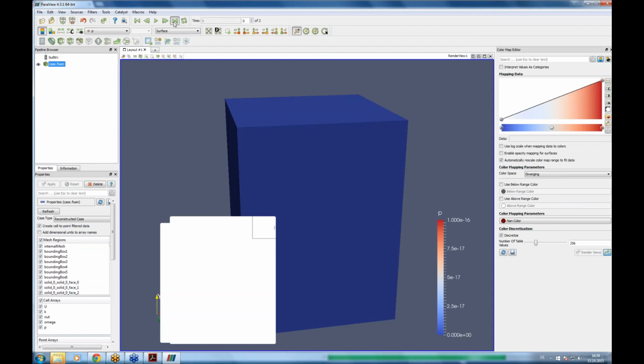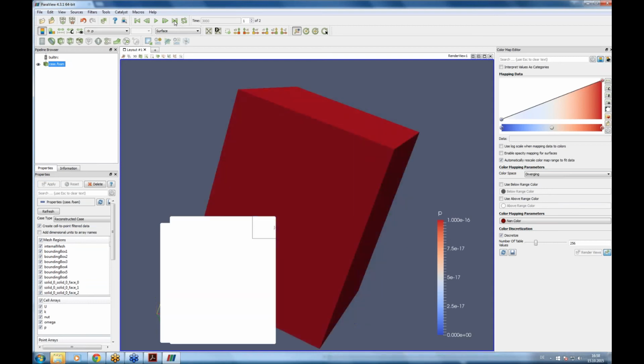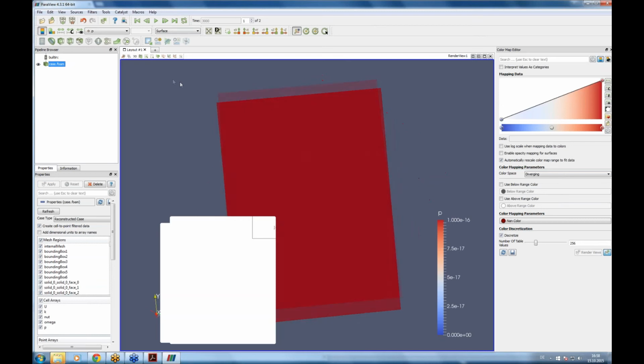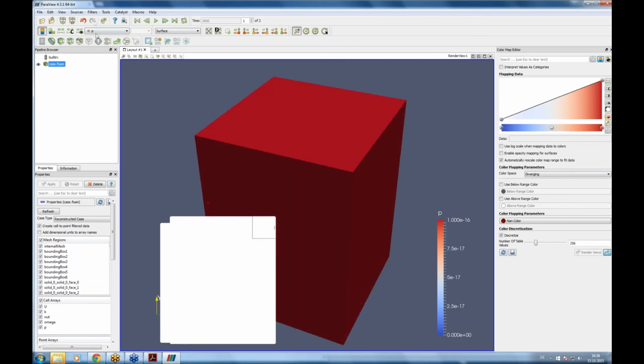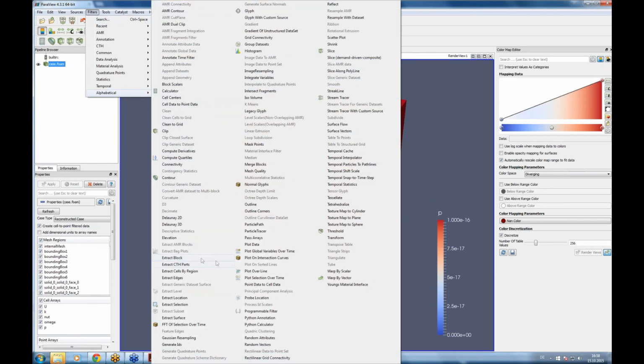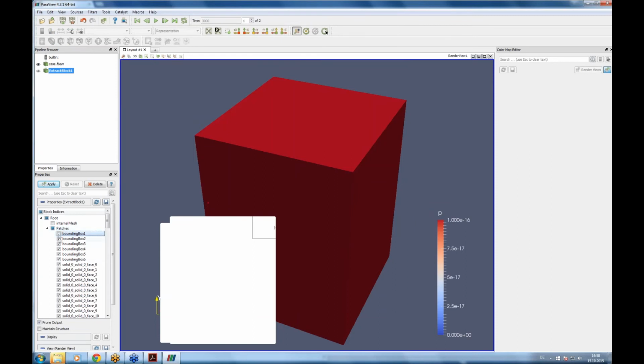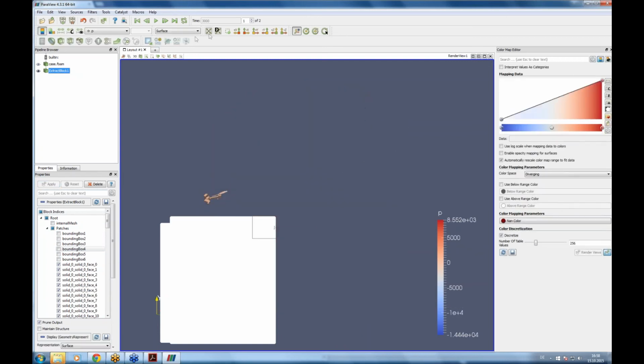So what I will do now is just jump to the latest iteration, so to the most accurate state of the simulation. And then, for example, I will extract all faces except the bounding box, so this is the surface of the drone for the initial design.